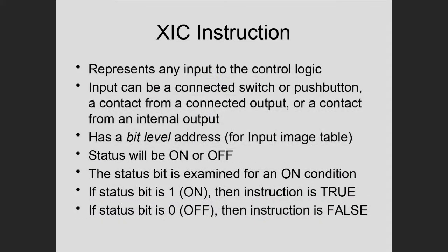So here's a little bit more about the command. We don't care what kind of input we have. It could be a button, it could be a switch, it could be whatever. It doesn't matter what kind of input we have. Whatever kind of input we have, we're always going to use this symbol to represent the input. Each time you change the state of that button, it's going to change a bit in the input image table that's mapped to a particular cell.